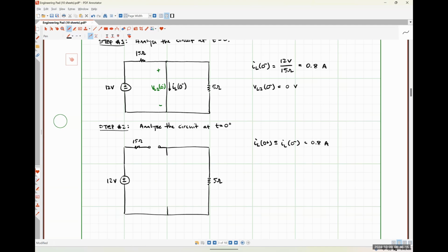The reason is that at this specific point in time, the current flowing through my inductor is a fixed quantity, while the voltage drop across it can be whatever it needs to be to make the circuit work, which describes the exact behavior of an ideal current source.